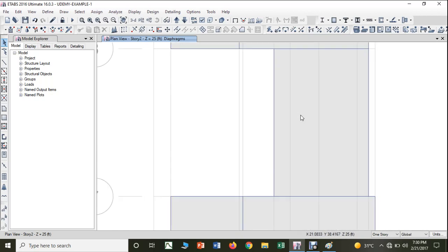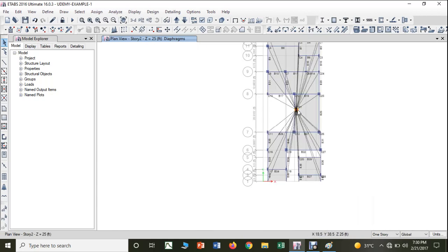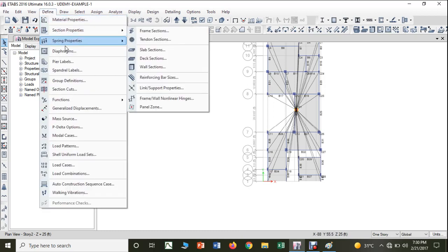Since there is an opening, you have a center of mass or the diaphragm center here. If you have something else, then definitely the position of the diaphragm will be some other position. It depends upon the plan of the structure. This is how it considers each and every corner of the slabs and makes the entire slab a single one, and it will analyze. That is what the define option in the diaphragm is for,